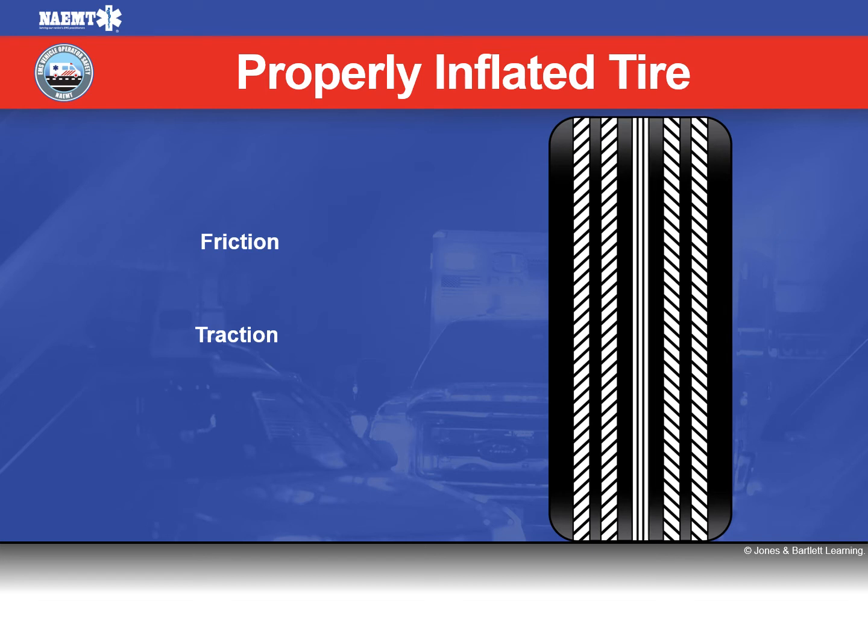An example: 32 psi times 10% is a 3.2 psi loss of air. A drop of just 20% of the tire pressure is enough to negatively impact handling, cornering, and stability. As an example, 32 psi times 20% loss is a 6.4 psi loss. This tire may not look or feel flat, and yet is extremely dangerous.